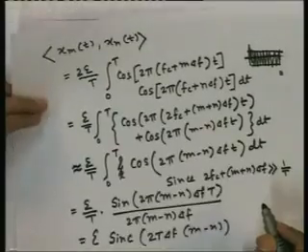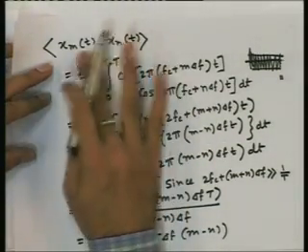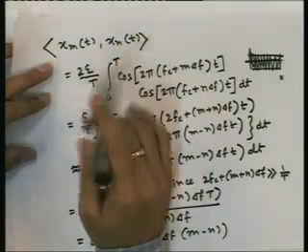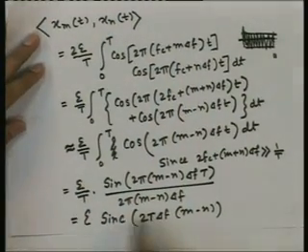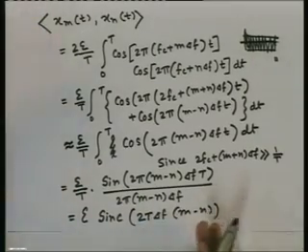So we have seen here that the inner product of any two signals of the FSK signal set is this. Now it depends on delta f. If we change delta f, the inner product will change. So for what all delta f will the signals be orthogonal?